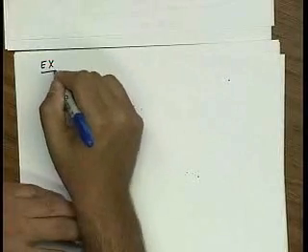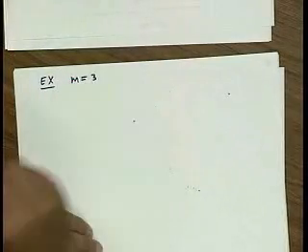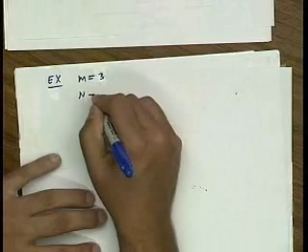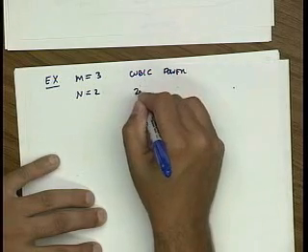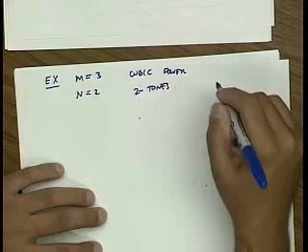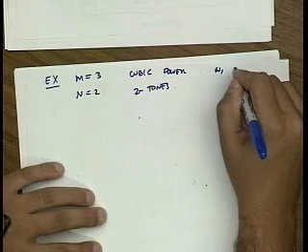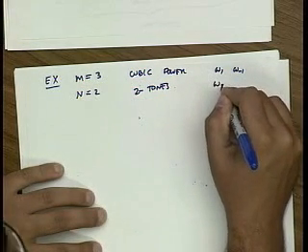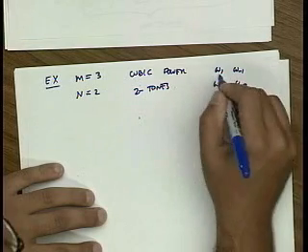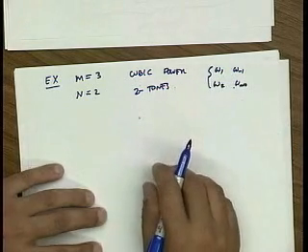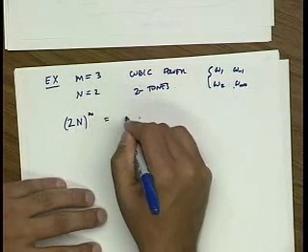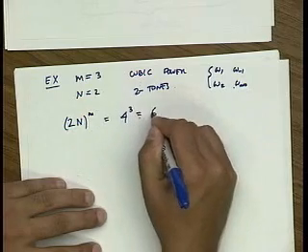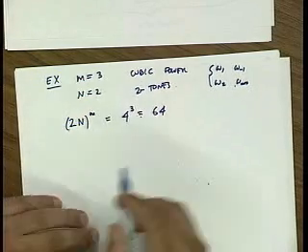Let's take an example to bring this home a little bit. Let me take something simple that we've dealt with. Let me take a cubic nonlinearity and two tones. So this is cubic power, two tones. And so my frequencies are omega 1, omega minus 1, and omega 2, omega minus 2, which of course is just minus omega 2. So how many terms do I have? I have 2n to the m terms. That's 4 to the third power, or 64 terms. So I have 64